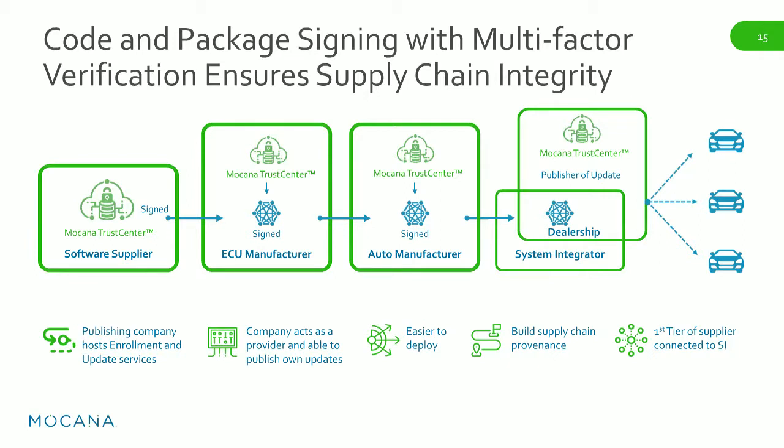So by the time the vehicle receives it, it should see 4 signatories, and it should see the package encrypted by the dealership using the certificate of the vehicle. So it's almost a very personalized drop from the developer to that vehicle in a way that along the chain, no tampering was possible.